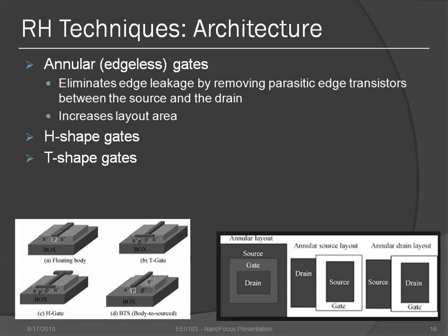So I also mentioned earlier that silicon on insulator substrates are a great technique for mitigating SEE, but susceptible to TID. In order to mitigate your TID, your total ionizing dose, on your silicon on insulator substrate, annular or H-shaped gates are often used.